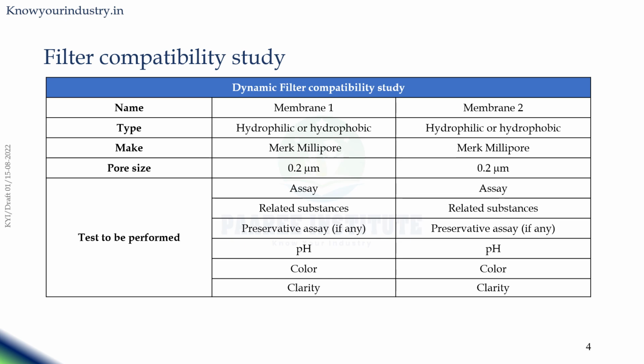This is a very, very important study because certain extractables or certain kinds of filter residues may get into your product while filtering the solutions, because the filtration happens either by vacuum or by the pressure generated using either nitrogen or compressed air.